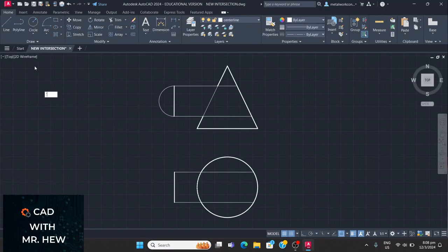All right, the next step, we're gonna cut the semicircle into 12 equal parts, okay? So we're gonna go line, and this angle would be 120. So that's what, 60, 60, that's the length at 120, enter, all right?